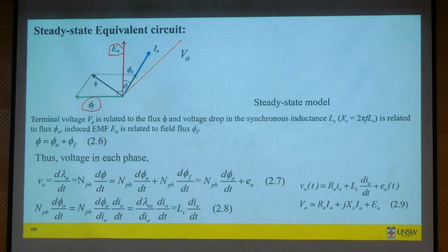But once the winding current flows in the winding, it also induces a flux, right? So that's your stator flux, okay? The stator flux is always in phase with your current, okay? So stator flux is in phase with current, and rotor flux has a perpendicular or 90-degree phase difference with your back EMF. Okay?